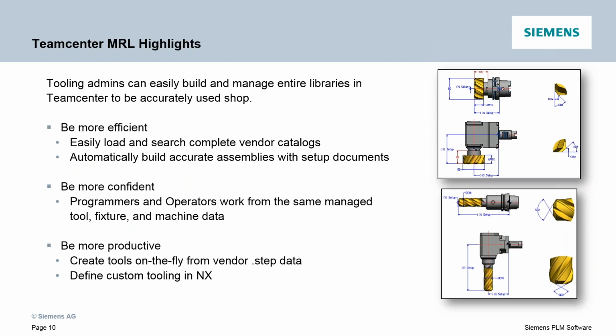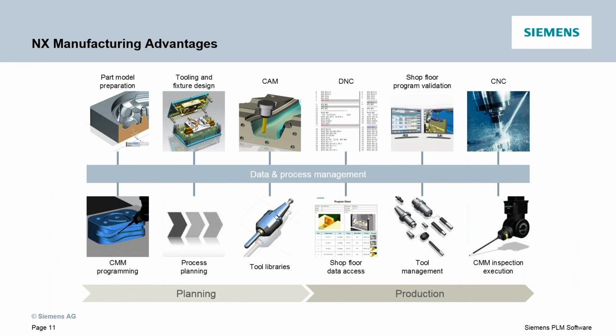People spend a lot of time creating setup sheets. So tooling admins can do all this stuff and be more efficient, more confident, more productive. That's the point of it. I don't want to sell you on the fact that it's just going to plug and play. You do need to set up your tooling libraries. Any good shop spends time managing their tooling libraries. So you do need to set it up, at least the first time, to get going. I highly suggest you spend some time and make sure you get your accurate tooling libraries set up as you'd like to use them.